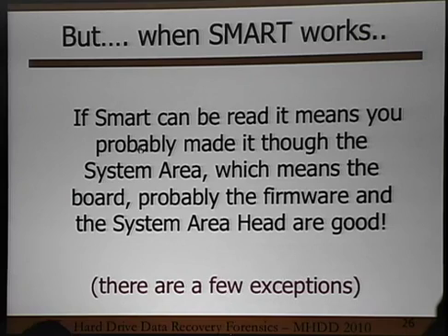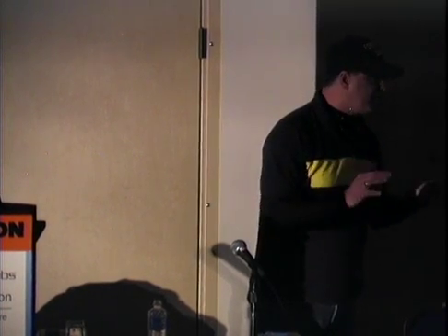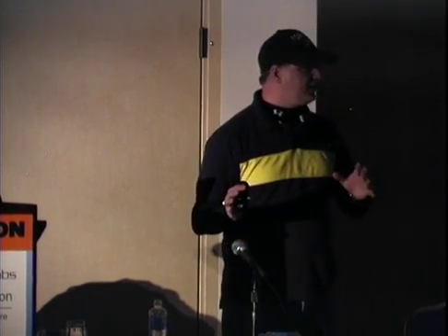But ultimately, my whole point is now I know to stop, because also what happened if the head read data from SMART and returned it to me, what else must probably be good? The controller, the board, the controller, and your firmware is probably at least running, right? You've probably at least made it through that part.